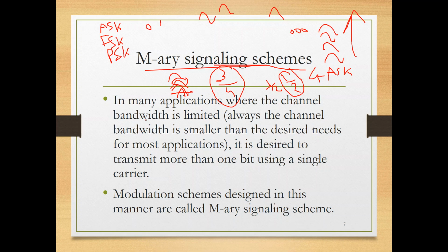What do you suggest? A modulation scheme of higher order modulation, like 64, 1024 levels, so that each level can carry 6, 8, 10 bits. Why do I use this modulation? Because the signal to noise ratio is very high. There is no noise. If there is no noise, the receiver can still distinguish and differentiate between all these different symbols easily, and still send more data bits per level.